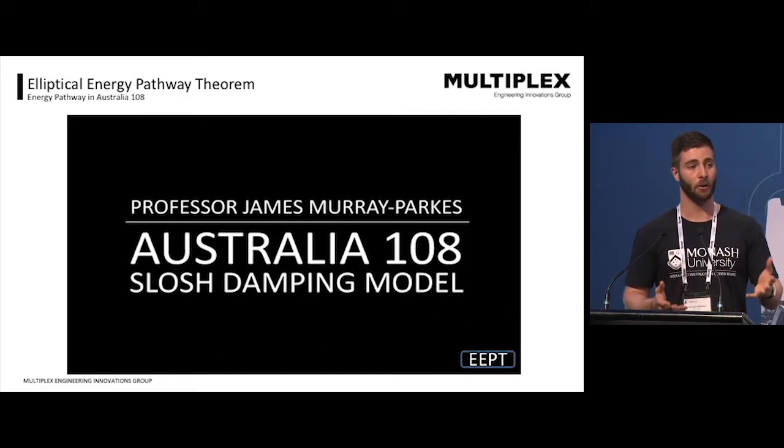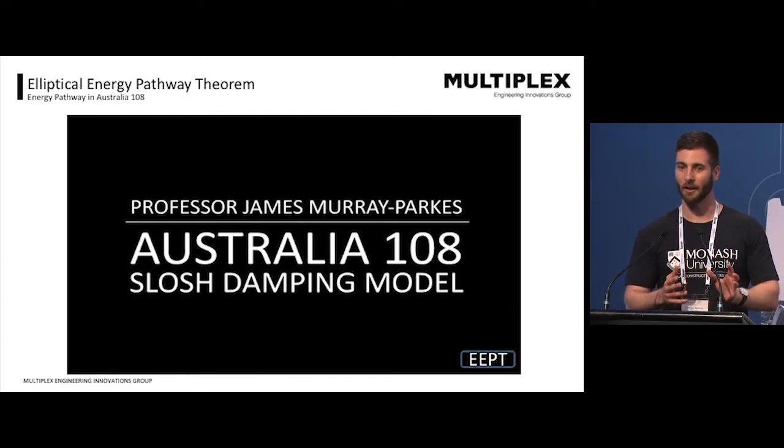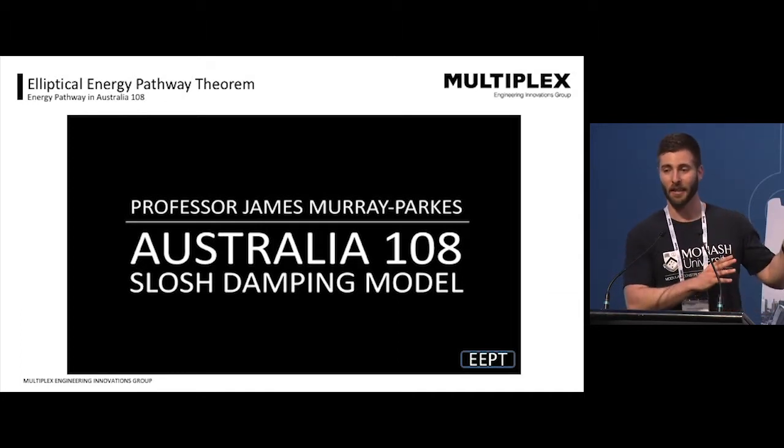So when we actually model this up, and like I said, we've got our guys back in the lab who are able to create our physical models. And we can see we make this model flexible so that when we have a different frequency of loading there, it's reacting in different ways, and we can quite clearly see how it's doing so. So we think that's also a really important aspect to the design in that we physically demonstrate, and you can see that equation I had up before doesn't mean anything to most people in here. But once you actually see that in action and how designing a building to that results in a different way that it's acting. And that's really the lesson I'm hoping to get across from this one, that by taking into consideration the physics and the maths behind it, we actually end up with a more efficient structure that acts differently and maybe doesn't require the additional measures to prevent all that movement in it.